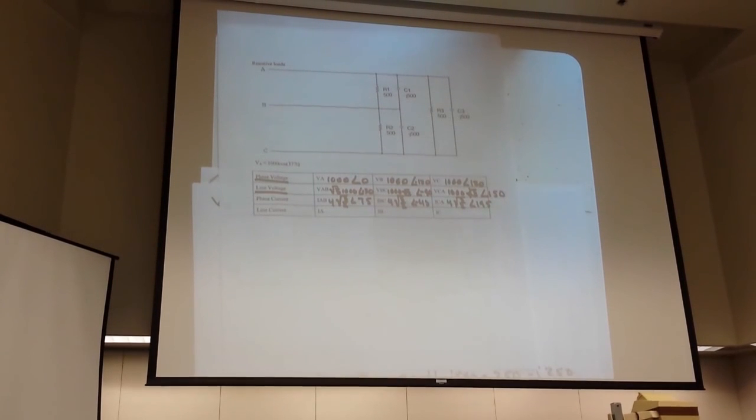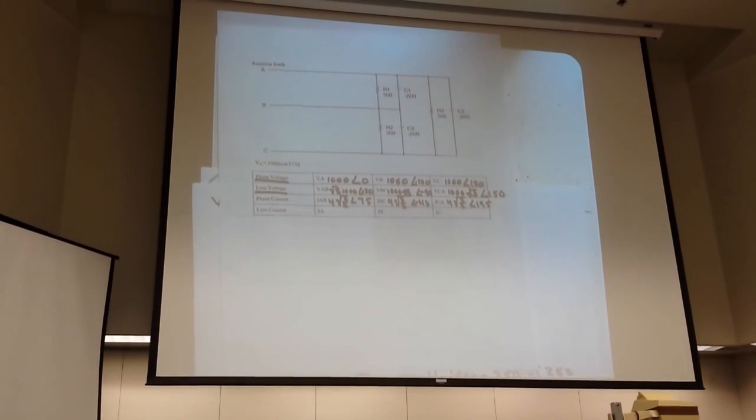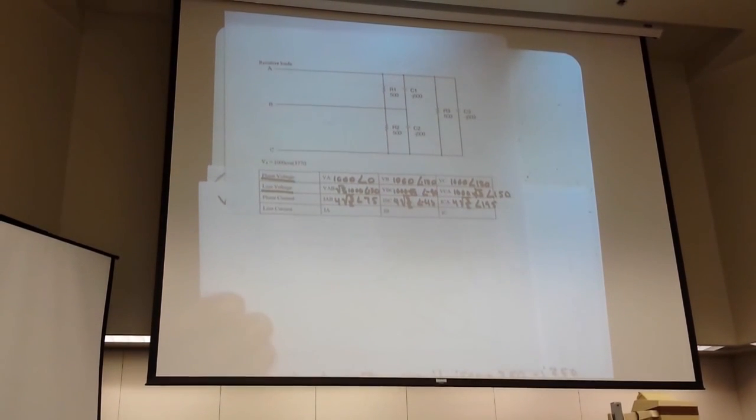And so now that we know the branch current, or phase current, what can we do? Well, we can get the line current by just using our square root of 3 relationship. Recall I line equals square root of 3 times I phase.